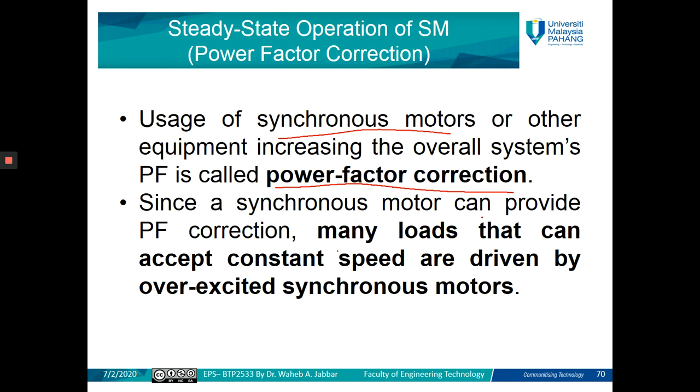Since synchronous motors can provide power factor correction, many loads that can accept constant speed are driven by overexcited synchronous motors. Why overexcited? Because in overexcited mode we have more torque, and also less power losses due to the leading power factor.